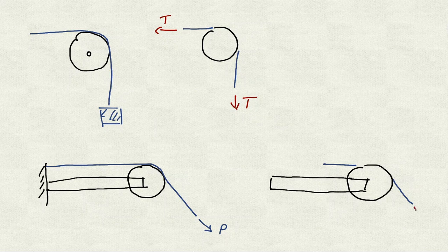So for example, here I would have the tension, as again it is along the rope. I would have a tension here. It is going to be along the rope. So both of them are tension. Both of them are along the rope. And also I have here, if I consider this point as A, then here I would have Ax, Ay, and M at A. So these are the reactions, these are the forces.